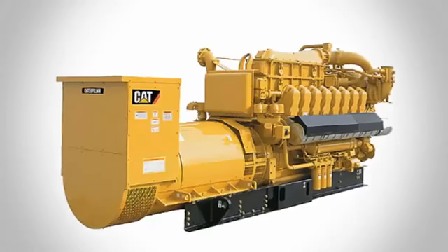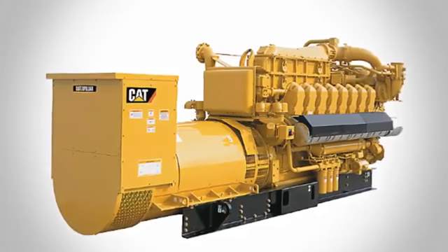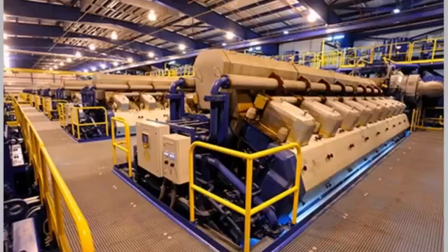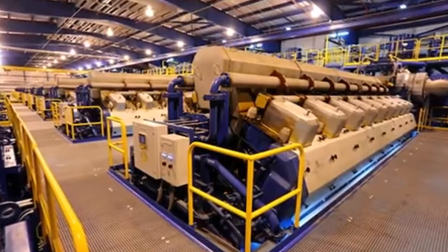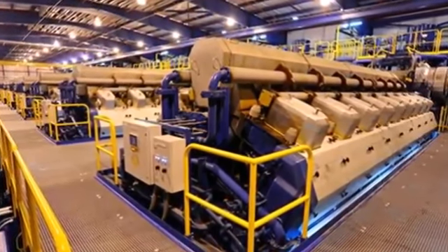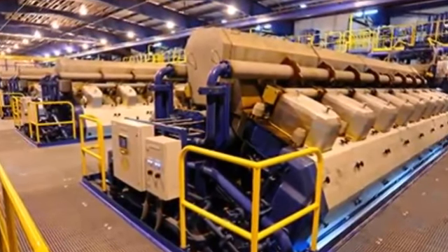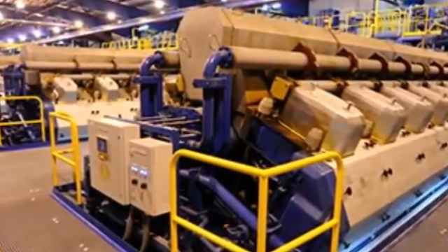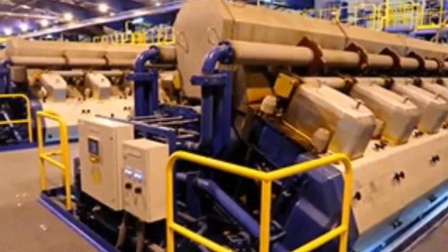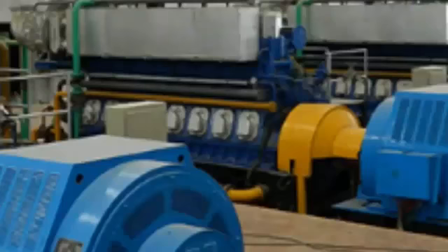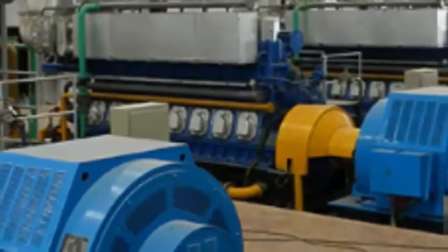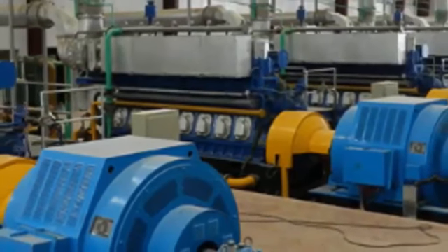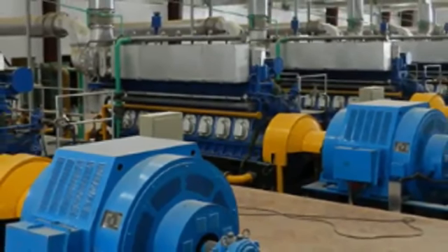As the generation cost is considerable due to the high price of diesel, such power stations are only used to produce small power. Although steam power stations and hydroelectric plants are invariably used to generate bulk power at cheaper cost, yet diesel power stations are finding favor at places where demand of power is less, sufficient quantity of coal and water is not available and the transportation facilities are inadequate. These plants are also used as standby sets for continuity of supply to important points such as hospitals, radio stations, cinema houses and telephone exchanges.